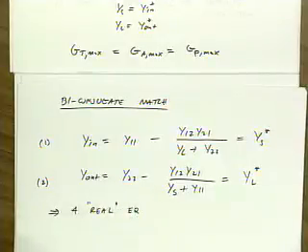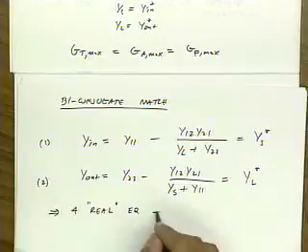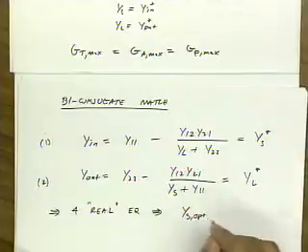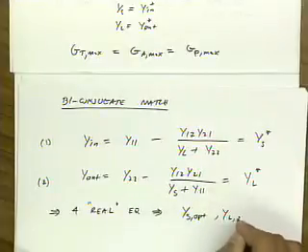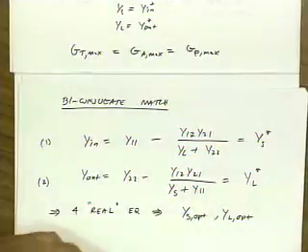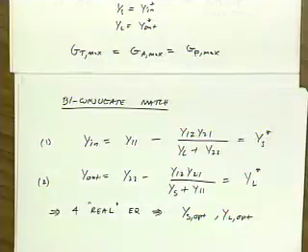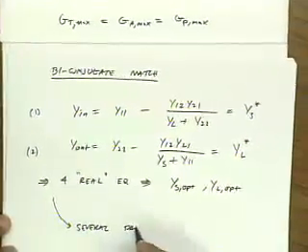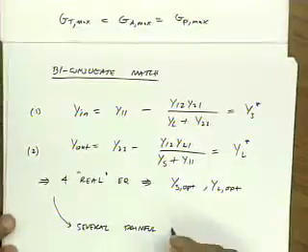Now, even though this is only two equations, it's really four real equations, because these are complex quantities, and we can solve for the unknowns: YS opt, real and imaginary part, YL opt, real and imaginary part. And you can do that, and what you'll find is several painful pages of algebra.